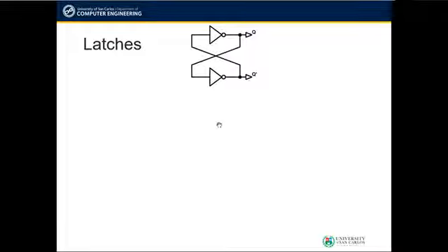We start by going back to the cascaded NOT gates we had in the discussion earlier, as shown here. If you can recall, NOT gates can be implemented using NOR and NAND gates by shorting together their two inputs to have a single input only. So therefore, this circuit can now become like this.